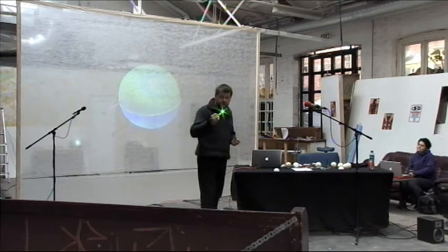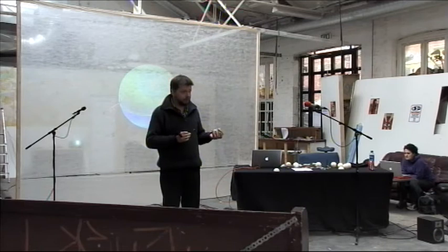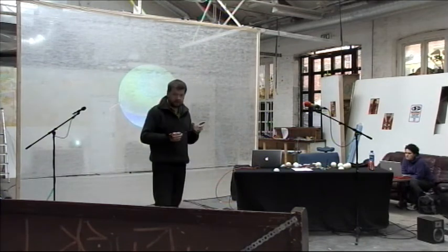These LEDs are way too powerful though, because they draw like 350 milliamps, and the battery that we use is like 250 milliamp hours. So if you had two of these on each side, you'd drain the battery in less than 20 minutes. And that wouldn't be good. So the blue side can go for different types of LEDs.